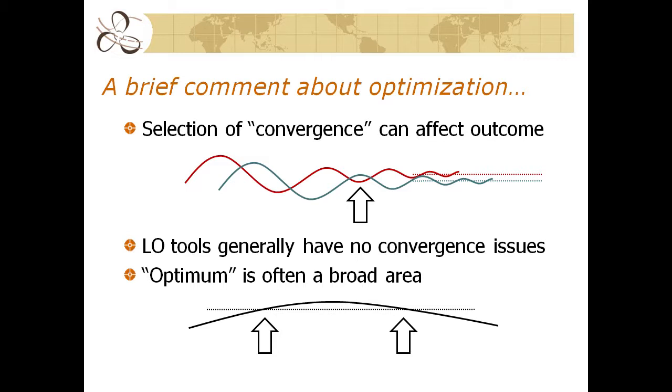Now, optimum and optimization, I used to teach an intro to naval architecture class, and it's great to watch students struggle with this concept of optimization because they think there's one perfect answer to everything. So they're looking for the peak of everything. And yet there's this huge broad gray area of acceptable solutions that are within 0.5%. And when we as naval architects recognize that we're juggling not only hydrodynamic performance, but structure and loading and cargo, and we have a business mission because we're designing a box ship that we need 200 meters of parallel mid-body that's wall-sided with a flat bottom, hydrodynamics is secondary to all of that. So we have to keep in mind what a rational decision for optimization really is.